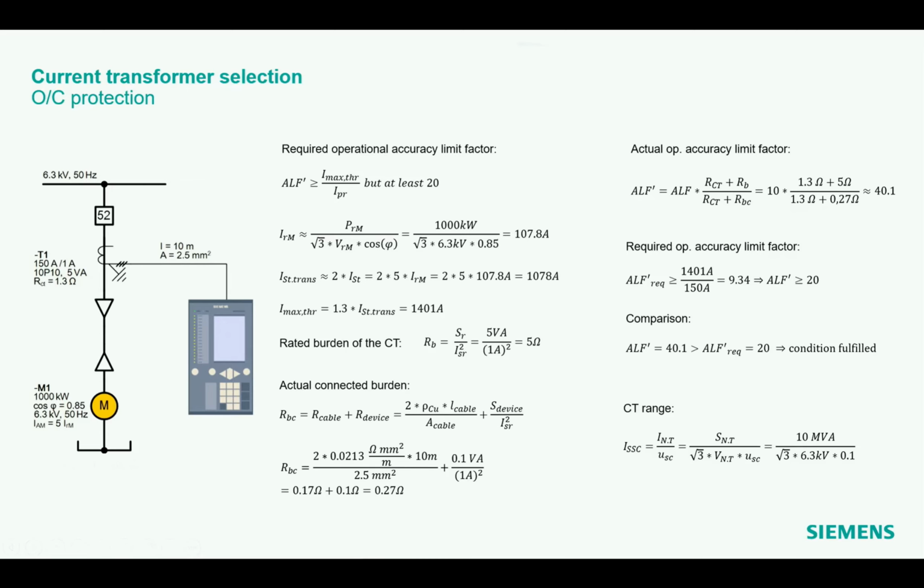If you don't know what USC means, it is this percent value at the transformer. And with that, we get an estimation. We always estimate a current which is bigger than in reality, because we do not consider any impedances upstream of the transformer, so we are always on the safe side.